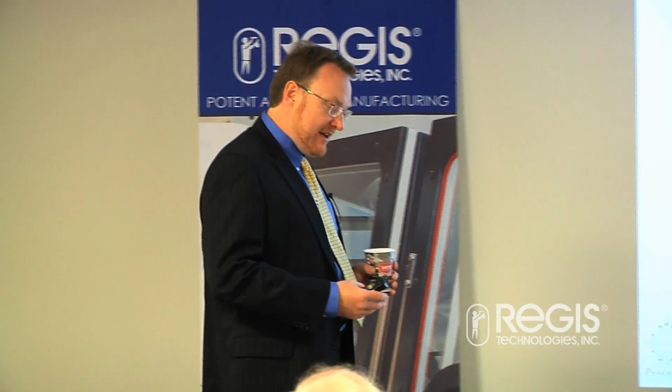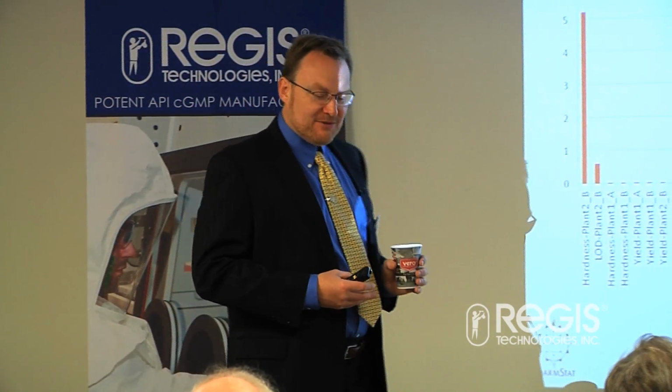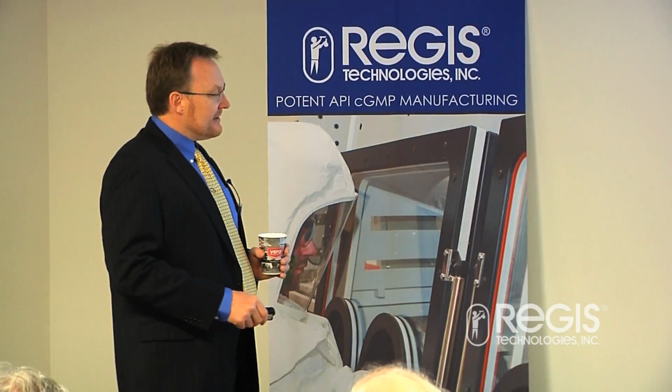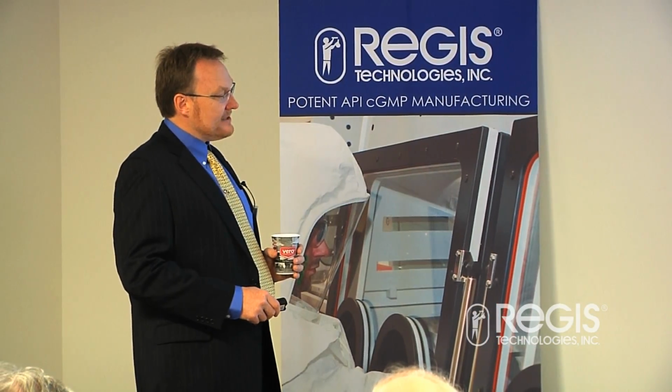SPC is actually the process of understanding the variation in your process, controlling that variation in your process, reducing that, right? As Shewhart defined it, SPC is actually a manufacturing management method. So let's institute an SPC process around the hardness of our tablets in plant 2 with product B and the loss on drying in plant 2, product B. Those might even be related.